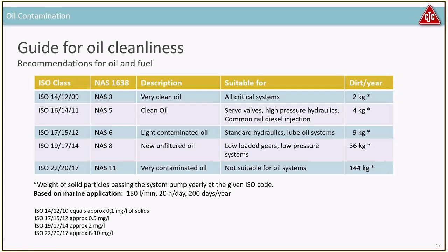That will of course wear the pump. While if you had a 16/14/11 instead, or a NAS 5, you would only be circulating 4 kilograms or 8 pounds.